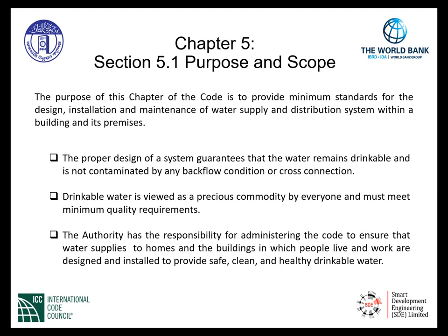So just reading that introduction sentence, you find that there are two different types of systems. The first one is called the water supply system. The second one is called the distribution system. The demarcation between the two can be looked at as the main shutoff valve at the building from the water supply connection that's tied to the main water at the public tap-in.